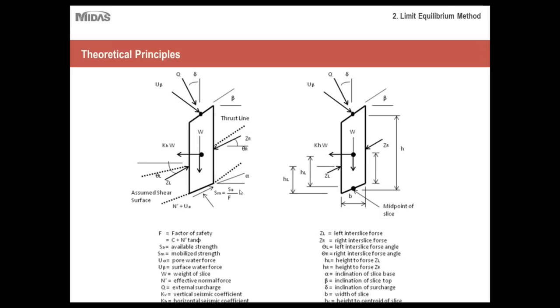Okay, so I won't go into too much detail about all the forces acting on the slices, but just keep in mind that the program takes all these forces into account when calculating your factor of safety. For example, the weight of the slice itself, the normal force acting back upon it, shear forces on the bottom of the arc, as well as interslice forces in both the normal and the shear direction, and any external forces acting down upon the slice itself. You can refer to this later when you're studying in your own time, all the different forces that are being applied to your slice.